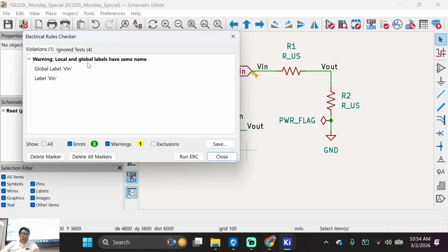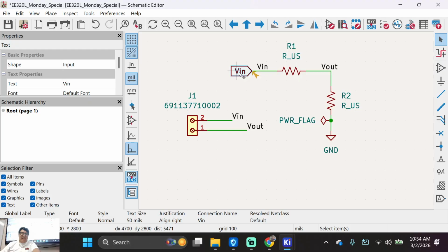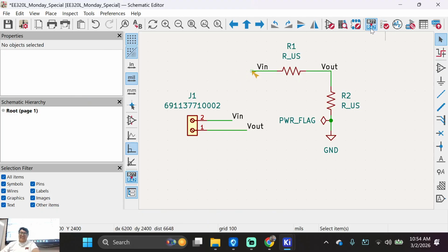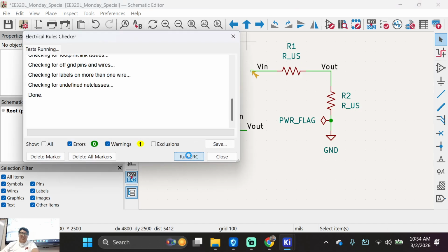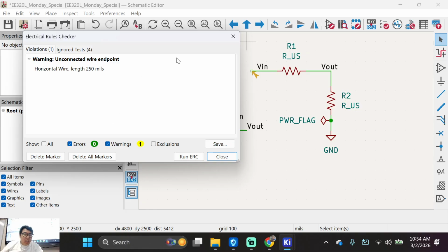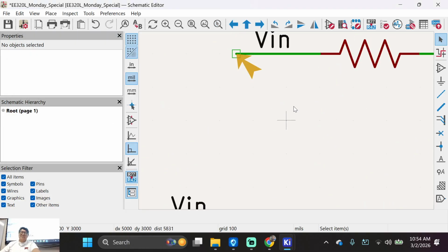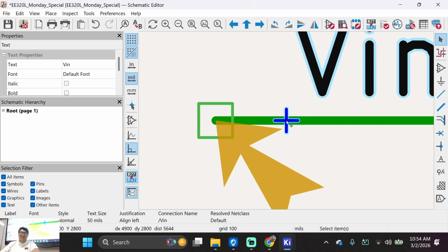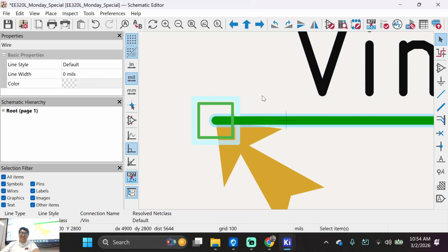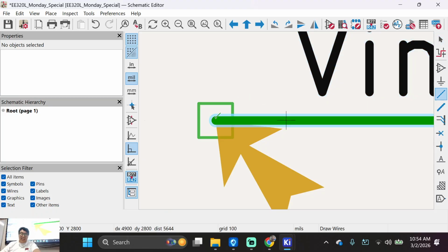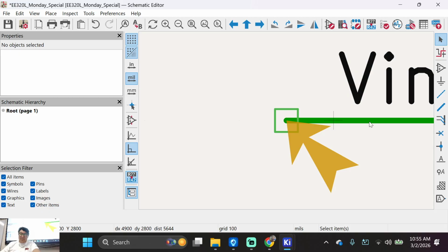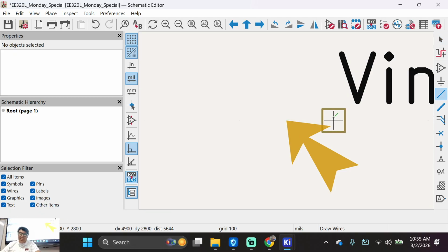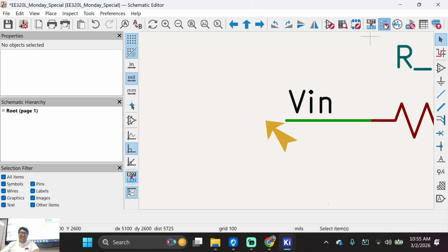Okay. Local and global labels have the same name. So what should I do? Just delete this, whatever. I want to go home. What? Unconnected wire endpoint. You want to know how annoying KiCAD can be? It's a little annoying. You see this square right here? You see this right here? Do you see this? If I just click and drag, let me just click and drag. I'm gonna click on this. Delete. I'm gonna press W here. And watch that error disappear. It's so...